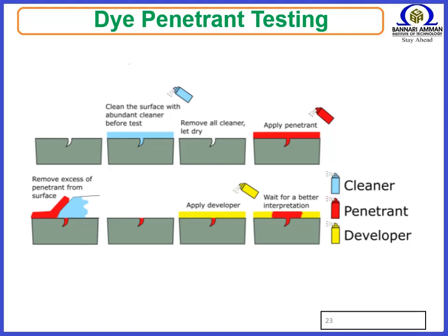Disadvantages: detects flaws only open to the surface. Materials with porous surfaces cannot be examined using this process. Only clean, smooth surfaces can be inspected. Rust, dirt, paint, oil and grease must be removed. Metal smearing from power wire brushing, shot blasting, or grit blasting must be removed prior to liquid penetrant examination. Examiner must have direct access to the surface being examined. Surface finish and roughness can affect examination sensitivity.